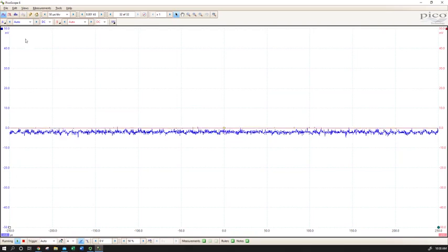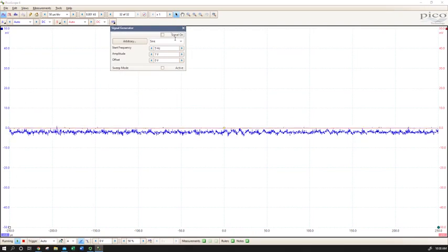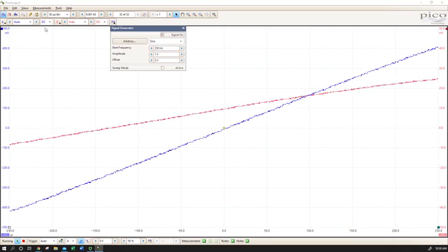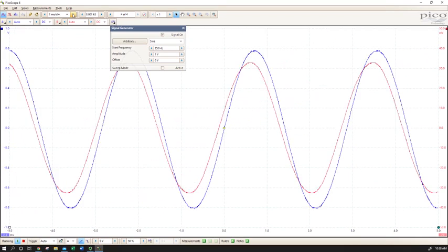We're going to go right over to our oscilloscope, and we're going to, let's try 350. First guess. We're going to apply that signal. We're going to increase our scale. Nope, almost, but not quite. Our resistor voltage drop is still leading our full circuit a little bit, but not much.